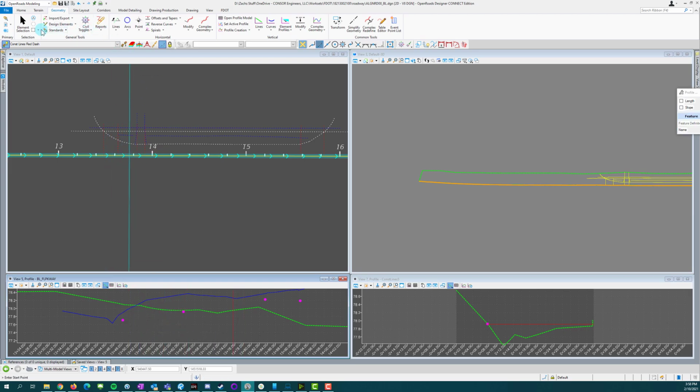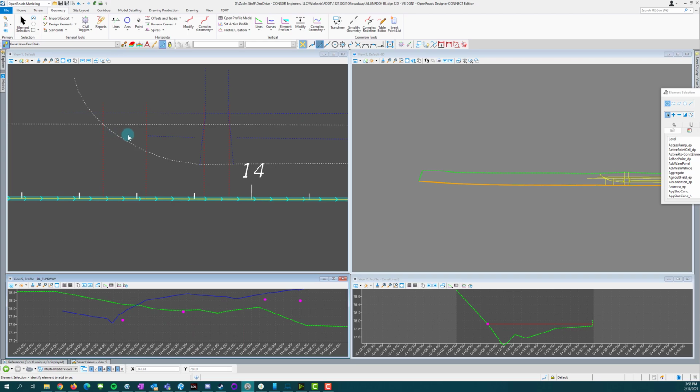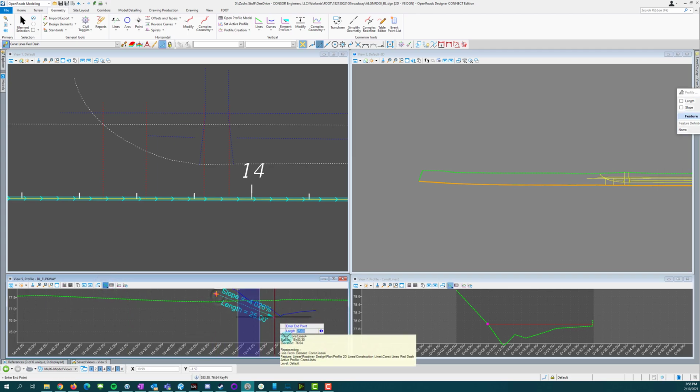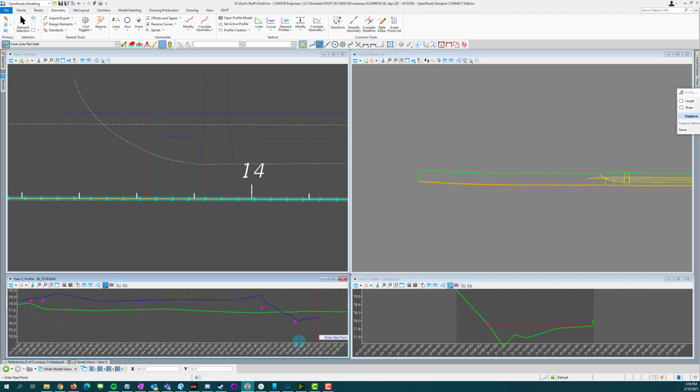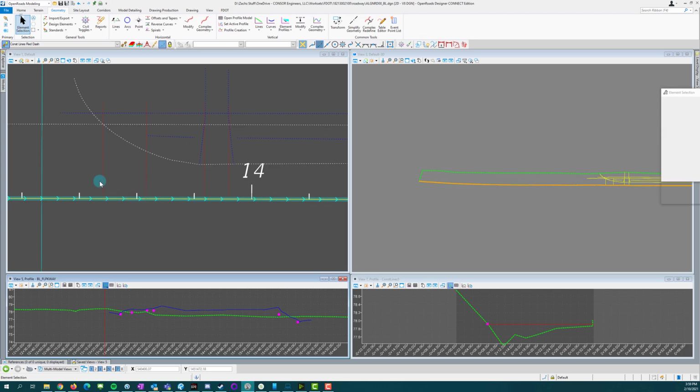If you wanted to make this a little smoother, you could always come in here and maybe offset this about 8 feet or so and create a little bit more of a landing here and then come up. That's an option as well. The whole concept here is just building your points from your back of sidewalk location along the center line. That's what we've done here. This one I can see is going to be a little bit steeper because we're coming down at 4%, but then we're going to go back up at 2% as we get into the road. So that's something to consider. For the sake of this exercise, though, I'm just going to leave it at those points there.